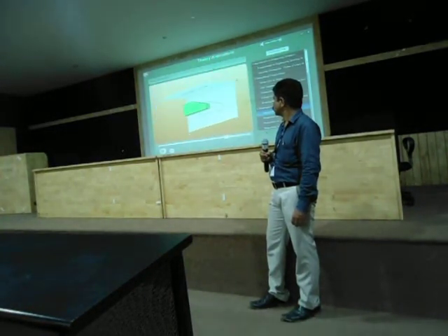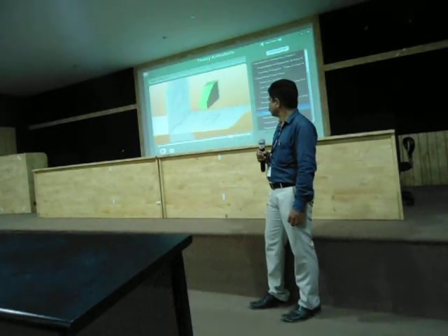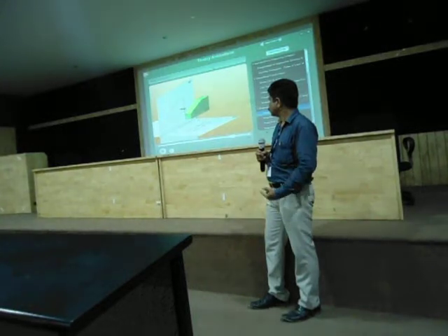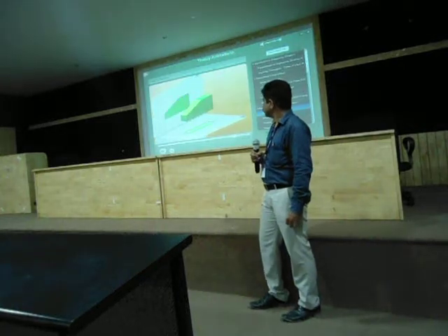Similarly, if an object is situated in the third quadrant, then the projection is known as third angle projection. In the first angle projection, the object lies above HP and in front of VP. The projection of the object is like a mirror image.